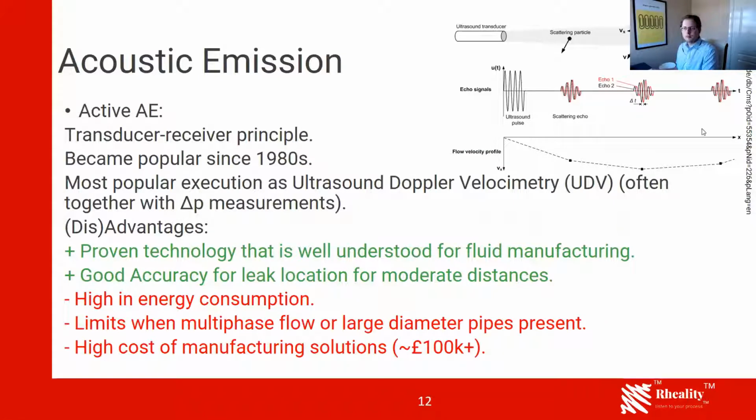There are in principle two technical executions. One is called active acoustics, the other is called passive acoustics. Active acoustic emission is a transducer-receiver system. I put a schematic up on the right side. It's not the newest of technology, it became popular since the 1980s. It's still in use. It's most popular as an execution called UDV or UDV-delta P, where they have ultrasound Doppler velocimetry measurement paired with differential pressure measurements.